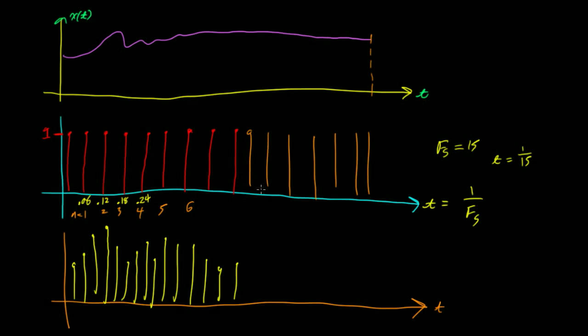All right, do these look like they're spaced every 0.06 seconds? So in 0.6 seconds, we should have 10 samples, right? So 1, 2, 3, 4, 5, 6, 7, 8, 9, 10. Okay. So that looks good to us. What I was saying before is if we actually fit a curve to these points, we then get an aliasing signal. So what we want to look at now